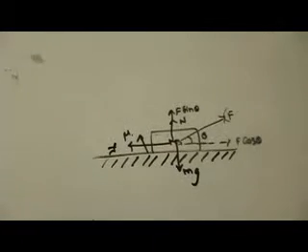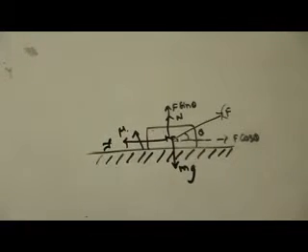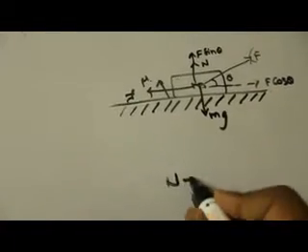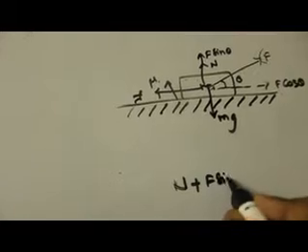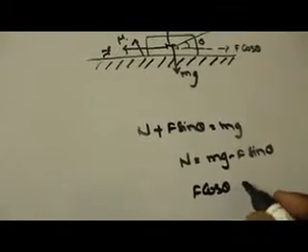As I said, it will have F cos theta and F sin theta as two components. And see, dear students, if I see the vertical equilibrium, what can I write from that? From vertical equilibrium, N plus F sin theta should be equal to the weight of the block, mg. From this, what can I write? Normal reaction is mg minus F sin theta. This is the normal reaction acting on the block. And you see, dear students, what is the horizontal component acting? F cos theta, just F cos theta is acting.